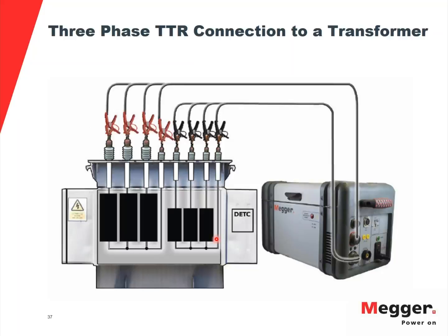But with winding resistance, sometimes the resistance can be really small for the low voltage winding, and meeting that criteria of 2% within the phases or 5% from the nameplate is hard, because you are trying to measure a few hundred microohms or a very small value, and 2% of that could be overtaken by the instrument accuracy.